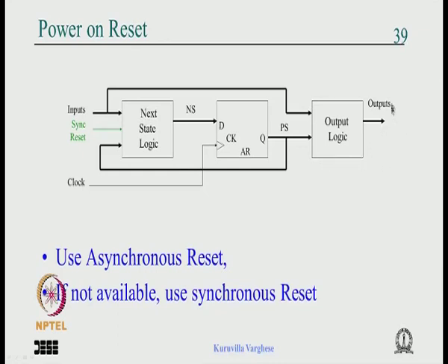Definitely if it goes through some other combination circuit to a register, we have to consider all that, and that is what, when you really design, the tool is going to look at the whole path. This is just a picture, but ultimately when you design, this is going through a register, output logic, some combination logic, and ultimately it is going to a register, and the tool is going to analyze that, that you should keep in mind. So let us put the maximum frequency, okay.